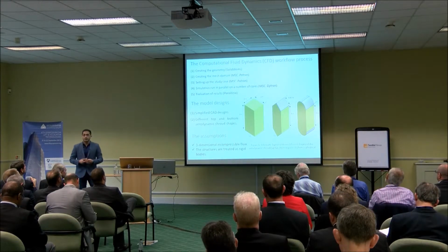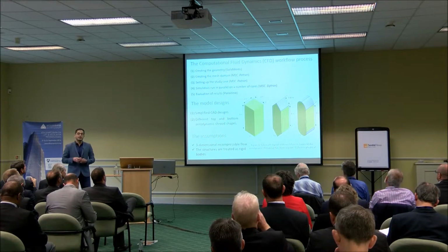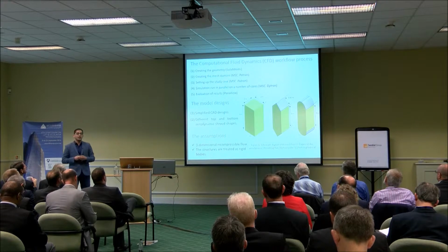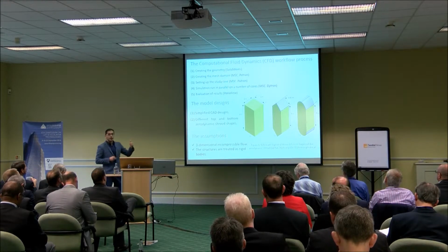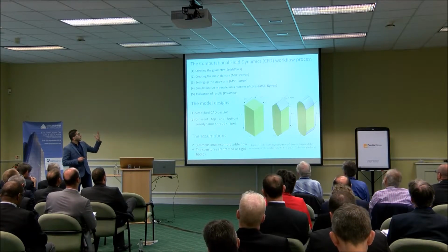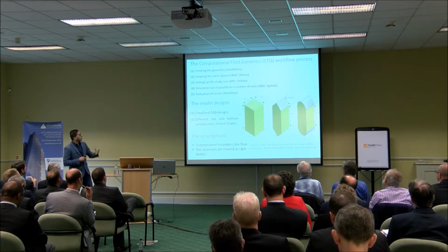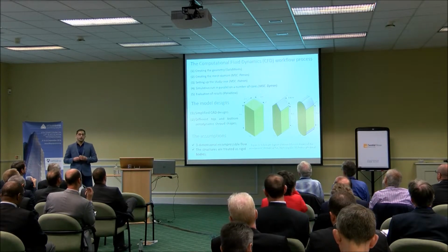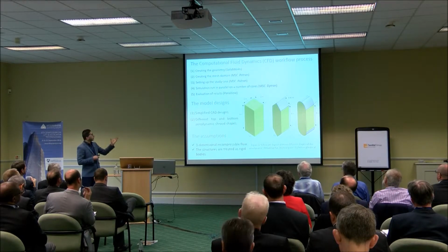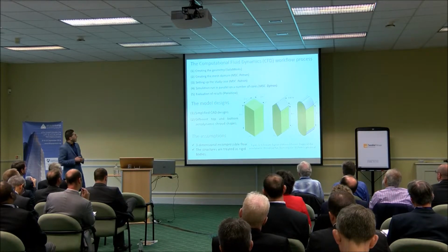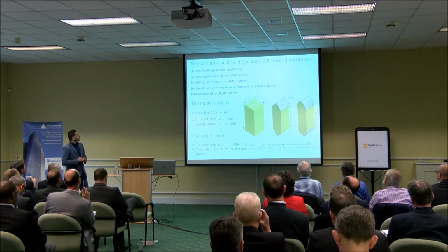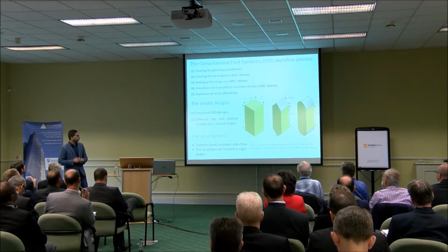The computational fluid dynamics modeling process has been done by using different commercial platforms. It involves creating the geometry using SolidWorks software and creating the mesh domain and setting up the case using MSC Patran software. Also, MSC Dytran has been used for the simulation run in parallel. Eventually, visualizing the results by using ParaView software.